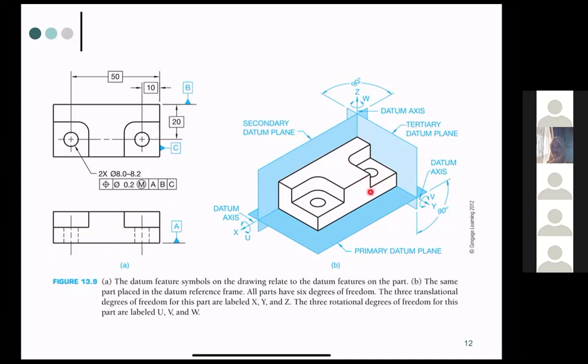From the front, if there's nothing inside, we can't see the hole, but from the top side we see that there are two holes, with center points and an axis there. So here we can draw that there's an axis and a hole inside it.